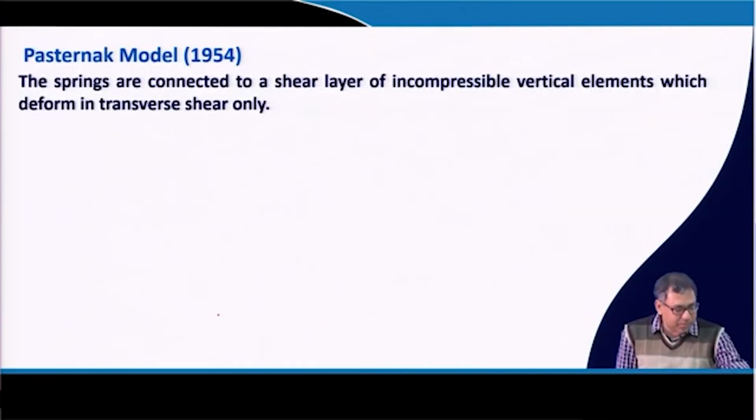Now, the next model is proposed by Pasternak, where the springs are connected with a shear layer. In the first or second model, the Filonenko-Borodich model, the determination of T is very confusing, that is, which value we will consider for T. So, to represent the real soil condition, this model is more suitable, or it can be applicable to this real life problem also.